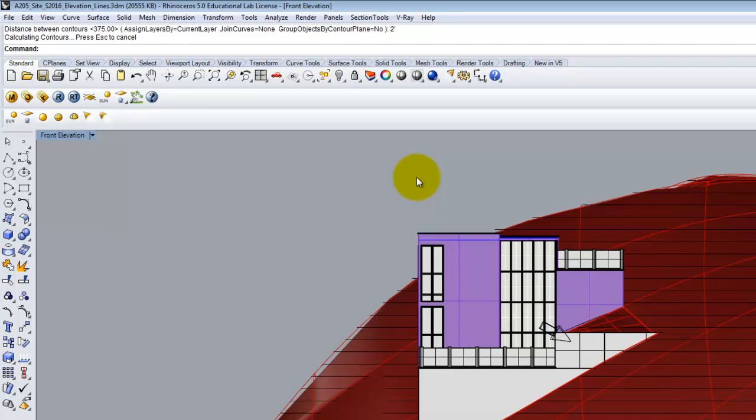Okay. So now what we need to do is take this three-dimensional view and make it into a flat drawing of lines. Rhino has an absolutely fantastic command built into it that's called Make 2D. What Make 2D does is it takes any view that you see and it creates a line drawing of that view. That line drawing is then flat, and we can use that as part of our export.